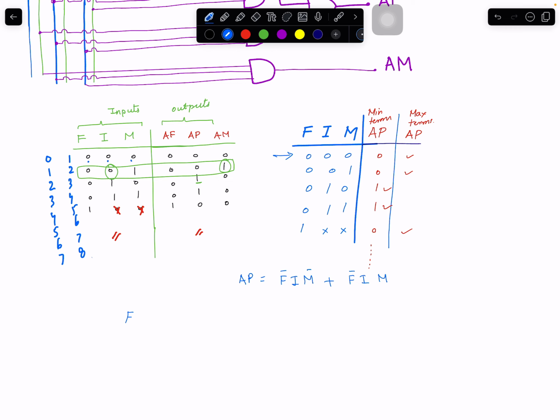So basically what we were picking was the one, if F gives 0, to make it 1, this needs to be inverting. This needs to be inverting. This needs to be inverting. Only then this becomes 1 because these are ANDs. The output of an AND will be 1 if all inputs are 1.